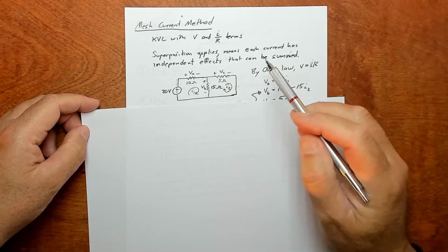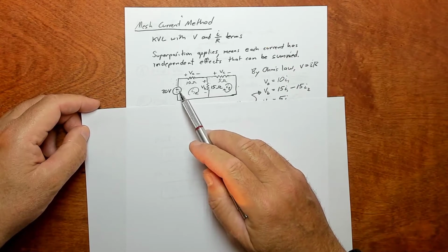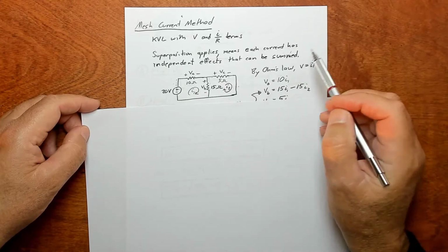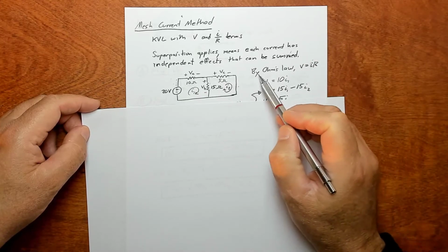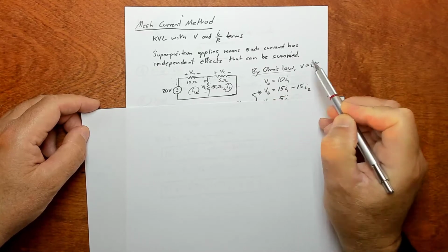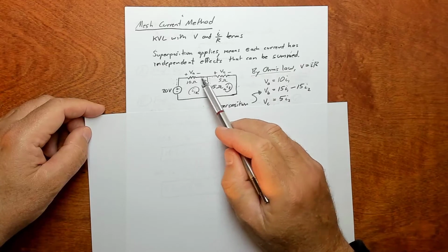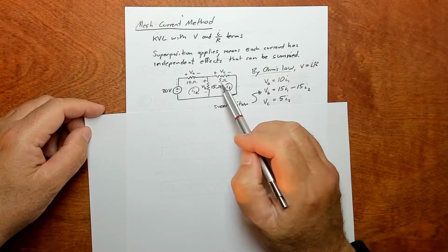Very same circuit. Oh, except I have a voltage source instead of a current source, so that is different. Okay, there's a 10 ohm resistor, a 5 ohm resistor, a 15 ohm resistor. So we have our infamous Ohm's Law where we know V equals IR. So let's put polarities on this, or just check that the polarities are all good.